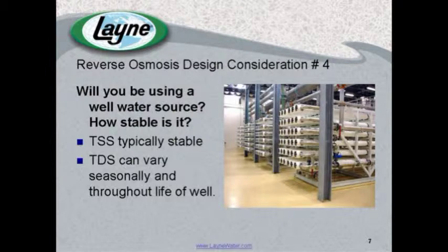And as those fluctuate, and they can, under extreme conditions, fluctuate wildly, you can really impact the effectiveness of your reverse osmosis system. So consider your inputs to your system, both surface water and well water, and make sure again that you have mapped out in a process fashion what the highs, lows, and means are over an extended period of time, preferably through all of the seasons of the year, so you know what you're up against.